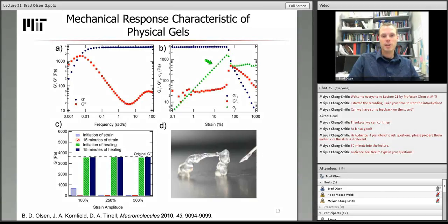This gives us another mechanism of tuning the response of the materials through changes in the molecular level associations and structure of the hydrogel material. And so this is one of the bases for producing shear thinning materials, and also a basis for producing self-healing materials, where the spontaneous reformation of cross-linked structures after the application of shear or after a responsive transition can enable a transition from liquid-like behavior to solid-like behavior in these types of materials.